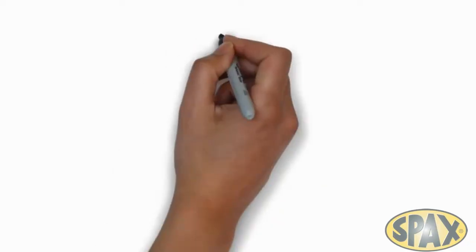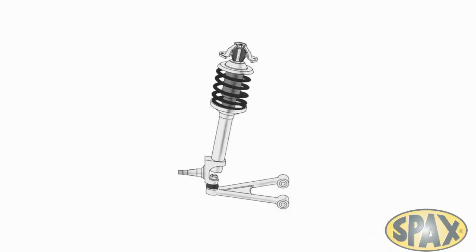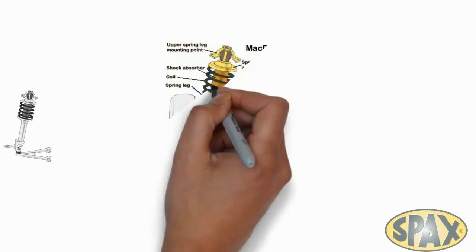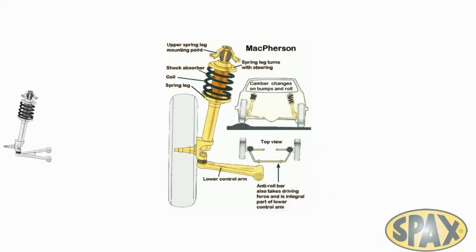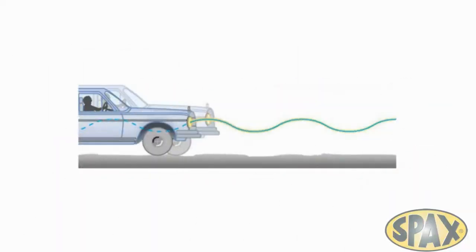Some suspension systems employ struts. These are a combination of a spring and damper, and they're used as a structural component of the vehicle. Struts, just like dampers, will help dissipate the movement energy produced as the vehicle travels, helping keep control of the car. They also serve to eliminate the need for other suspension components, for example upper control arms, and this minimises the unsprung weight and keeps down expense. So we've seen that dampers, or shock absorbers as they are called, are necessarily employed to dissipate the energy and smooth out cyclical response in a spring, literally damping energy to smooth the ride.